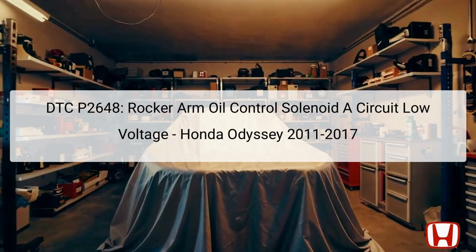The DTC P2648 refers to a circuit issue in the rocker arm oil control solenoid A, associated with Bank 1 in the Honda Odyssey models produced between 2011 and 2017. This diagnostic trouble code, DTC, indicates a low voltage condition which signifies that the solenoid is not functioning as intended.